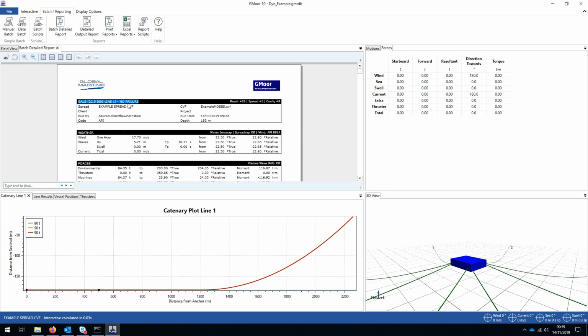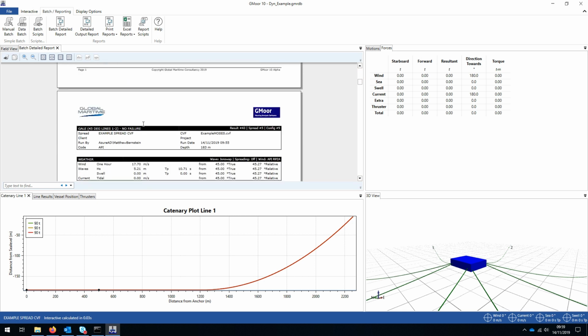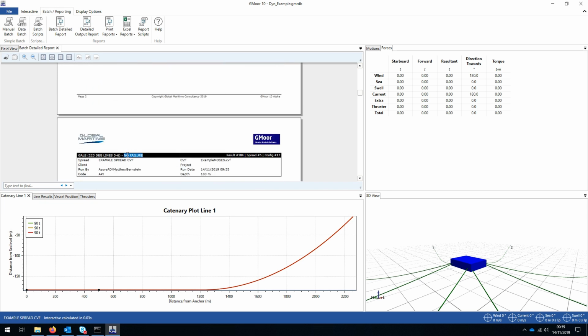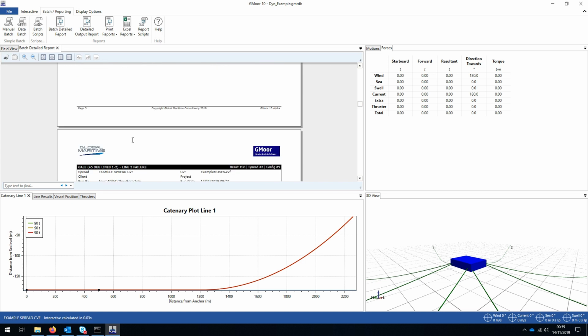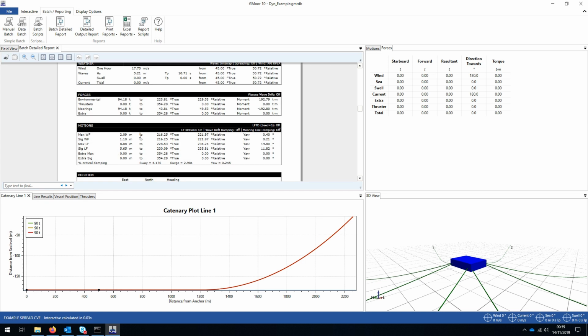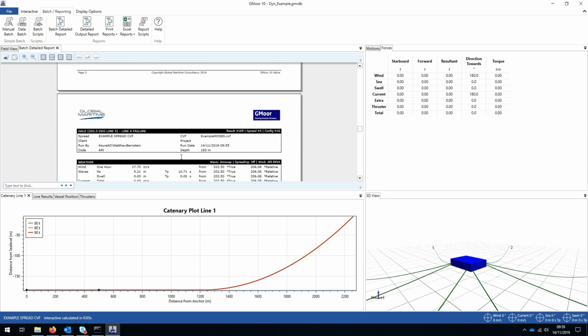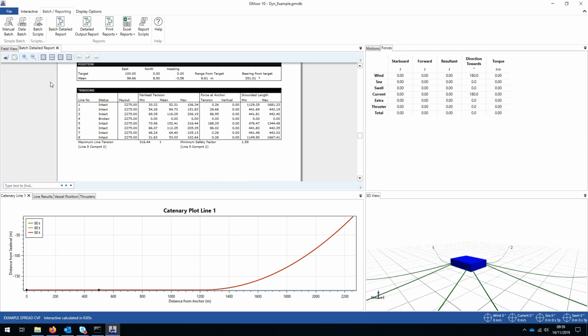So we should have 3 pages for no failure, i.e. intact. 1, 2, 3. Then we'll come on to single line failure, non-transient, 1, okay, we're actually interspersing, so we'll go single line failure, transient, single line failure, transient, but we'll get 3 of each. So it pulls out just the 3 worst cases for both. So that's particularly good if you don't want to go through a whole lot of reporting and pull out every last detail yourself.